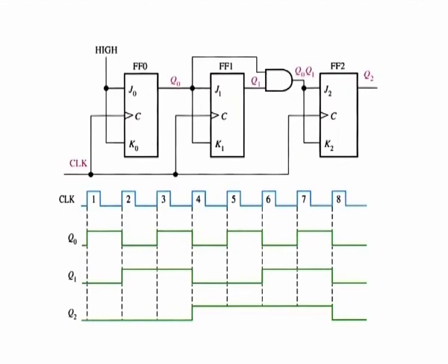Next, let us see how flip flop 2 is made to change at the proper times according to the binary sequence. Notice that both times Q2 changes state, it is preceded by the unique condition in which both Q0 and Q1 are high. This condition is detected by the AND gate and applied to the J2 and K2 inputs of flip flop 2.